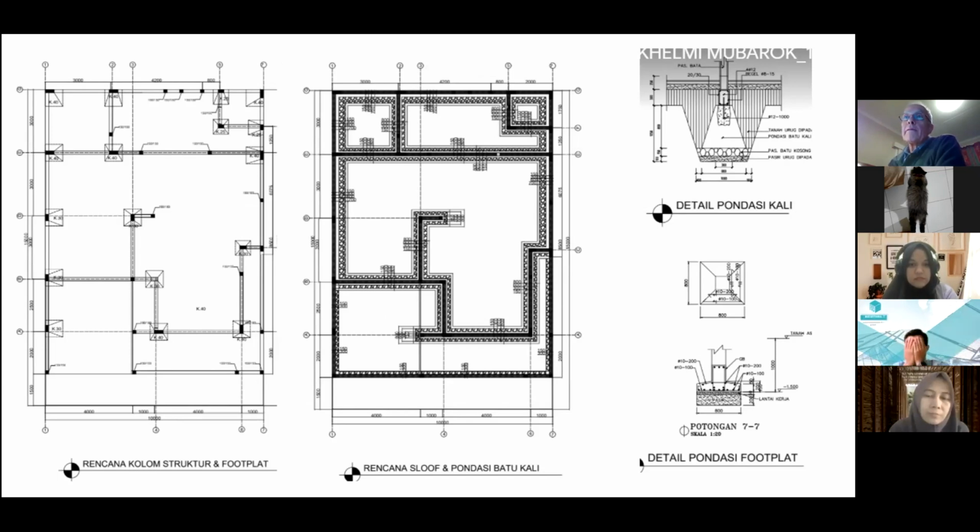Basically, we need a lot more beams, and the slab has to be thicker unless the student provides secondary beams, in which case we have more beams, but we keep the slab thinner. So it is possible to have the slab at 15 centimeters deep, but the student would have to provide additional secondary beams to support that slab. And those beams have to be shown in section and on the plan of the beams.